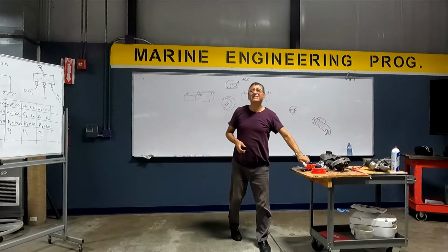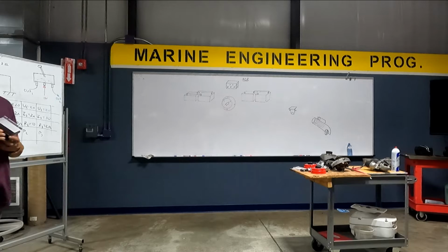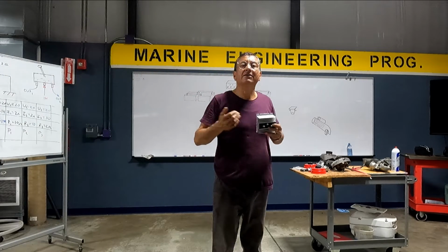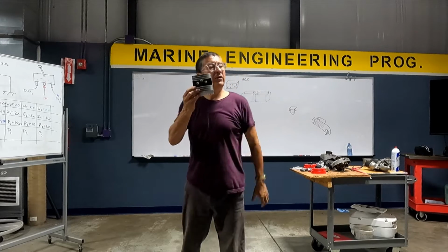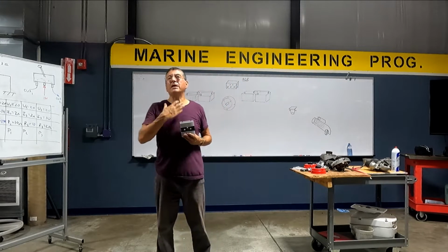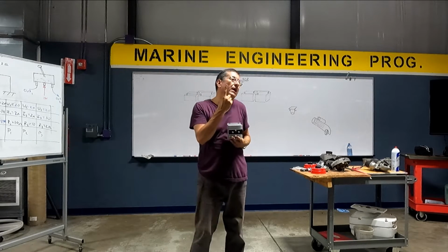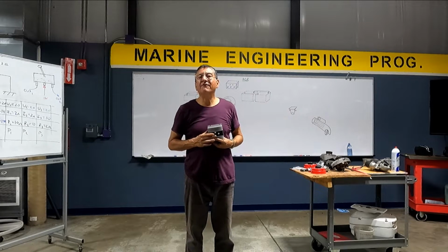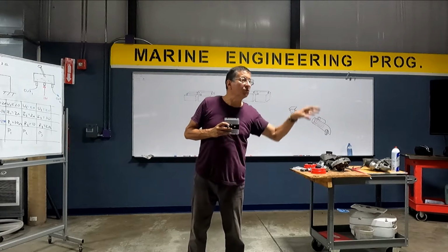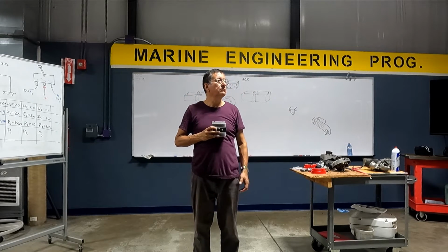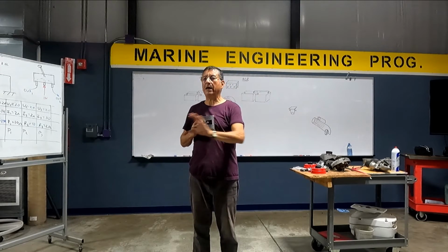And this is the A.C.R. What is the meaning of A.C.R? It's automatic charging relay, or a battery stabilizer, or battery equalizer. For example, suppose that I have in my boat only one engine, of course with one alternator. And I have in my boat two batteries. One battery for cranking and the other battery for the house. It's a small boat. Single engine, one alternator, two battery banks.